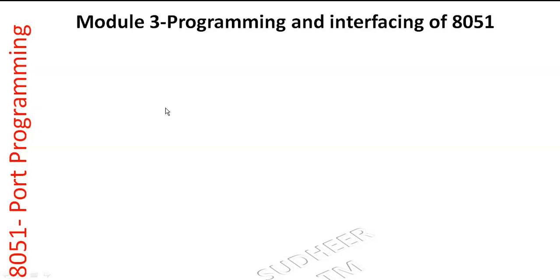Class is on port programming. So what do you mean by port? Our microcontroller 8051 has 4 ports. They are named port 0, port 1, port 2, port 3. Port programming means how we can configure these ports as either input port or output port.